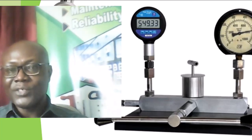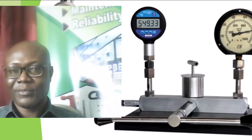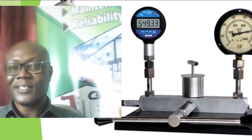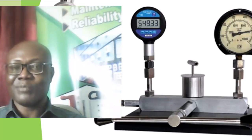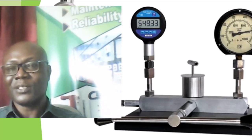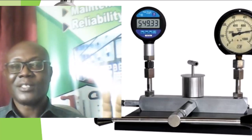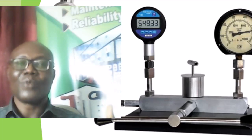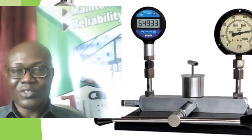And then we compare the readings of both of them. Are we getting it? So if the reading of the meter is the same as that of the trusted instrument, that means the meter is very reliable, it's okay. So we can leave it and continue to use it.